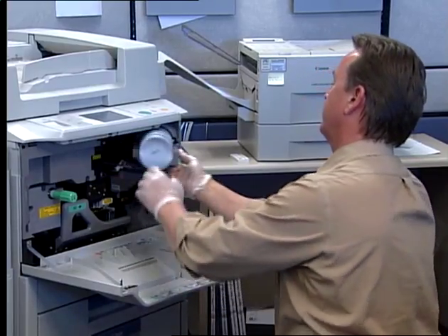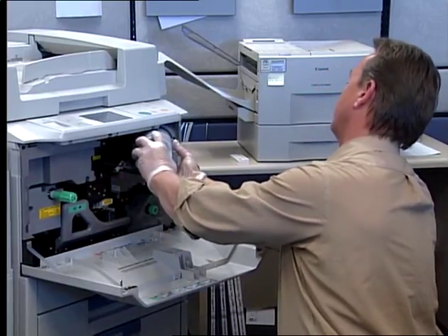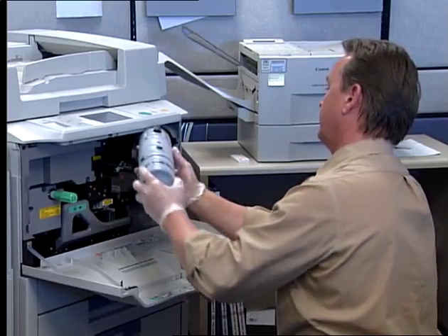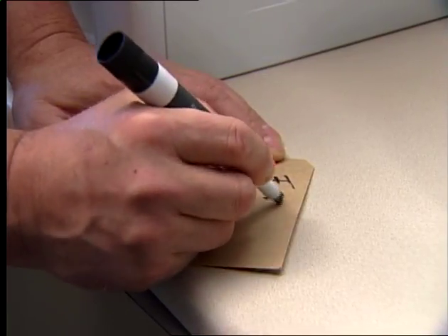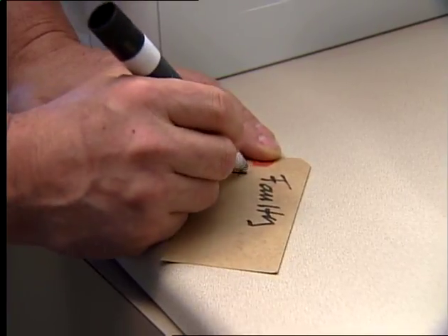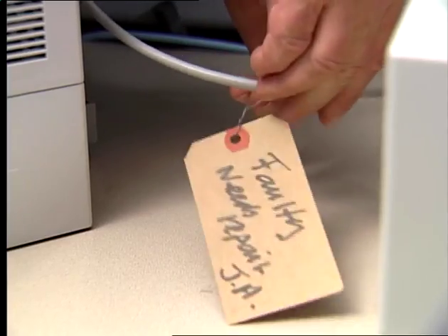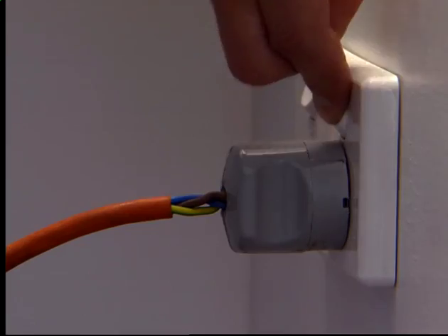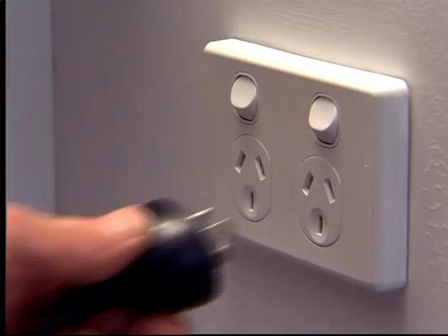All equipment should be well maintained. Substandard or poorly maintained electrical equipment is a hazard. Any broken or defective item of electrical equipment should be repaired or replaced immediately. If electrical cords are cracked, frayed or broken, disconnect them immediately and have them repaired or replaced.